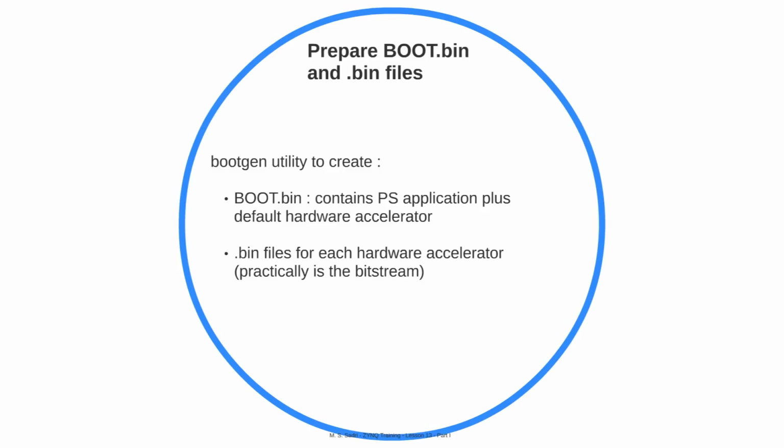But you may like to know, in fact, where you can find examples of how each of these two challenging tasks can be done. The first challenging task is to read the file out of the FATFS file system. The second one is to initialize and use the PCAP. And for both of these, there are examples inside your Vivado installation.